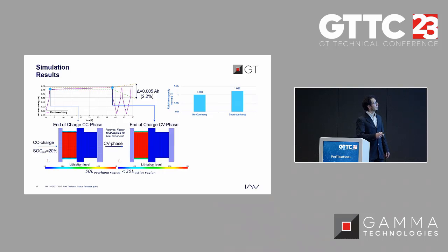Now switching to the time at the end of the CV phase, so 36 hours, then still we have a fully loaded active region of the anode. Still the cathode is empty, and we see some evolution in the anode overhang region with some filling, or partly filling of it, which shows here a very, very slow process.